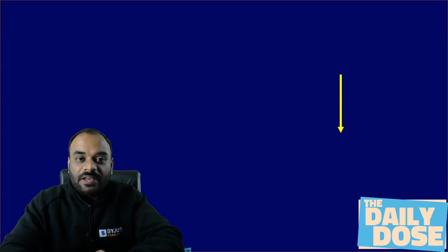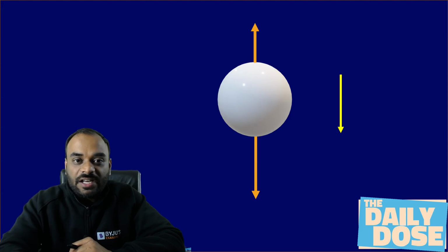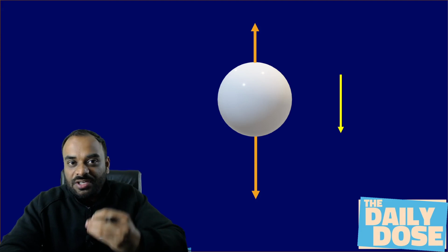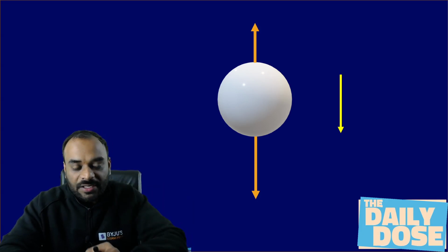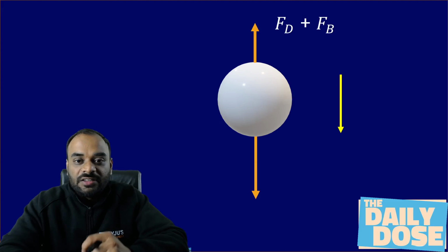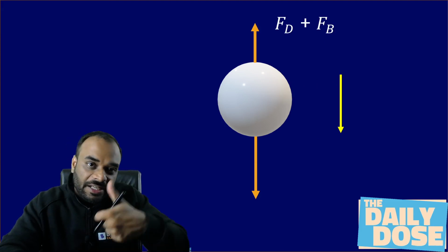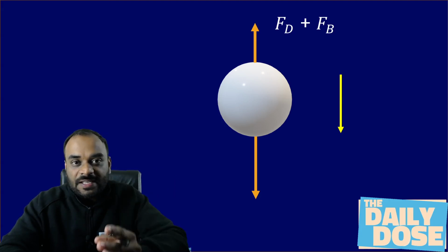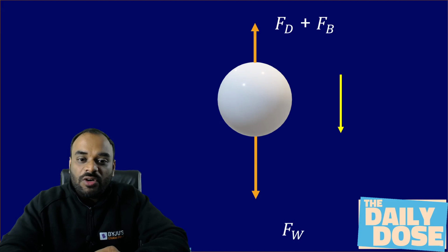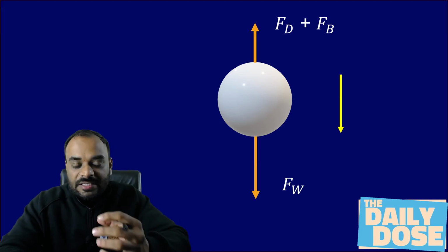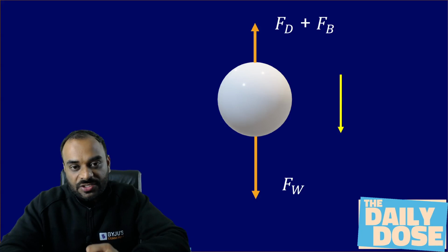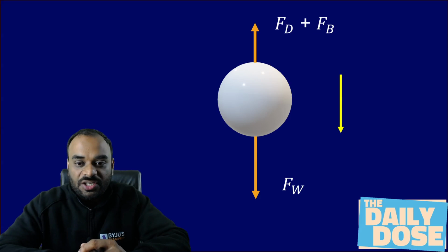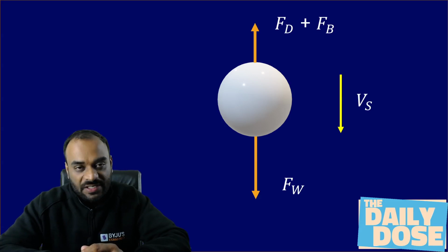So as you can see here, guys, this is the particle, right, which is trying to settle down in the sedimentation tank. Now there are various forces applied on this particular particle. The first two forces are the drag force and the buoyant force, which are applied in the upward direction, right? Fd is our drag force, and Fb is our buoyant force. The second one is the self weight of the particle, which is applied in the downward direction. Now after balancing all these forces, our particle is trying to settle down in the downward direction with a constant velocity, that is Vs, right?